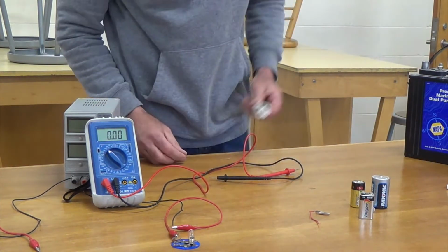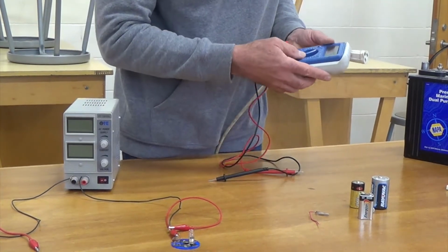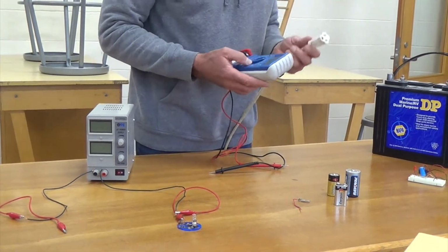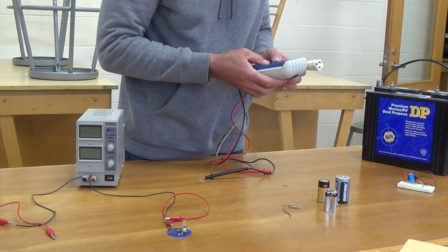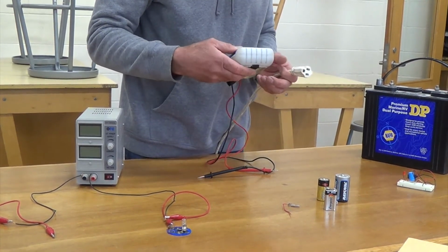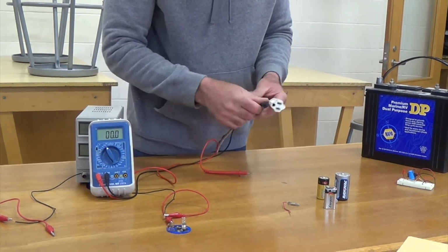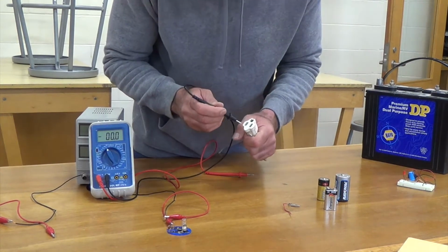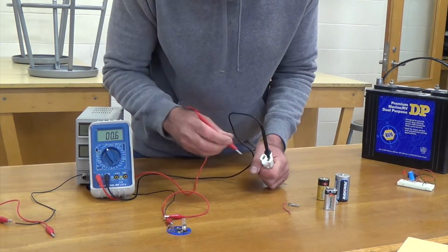So how much is flowing through this? And that's where you've got to be careful. I wouldn't do anything like this at home, but I've got to change it first of all to AC, which is alternating current, and I've got to put it on the right voltage a little bit higher, so I don't ruin my meter. I've got it set a little bit higher. Now if I take my reads carefully so I don't touch any metal while I do this, I stick that in there, and then I stick this one on this side.